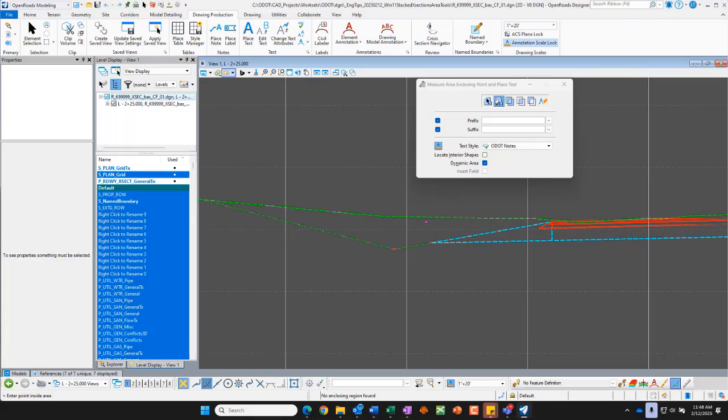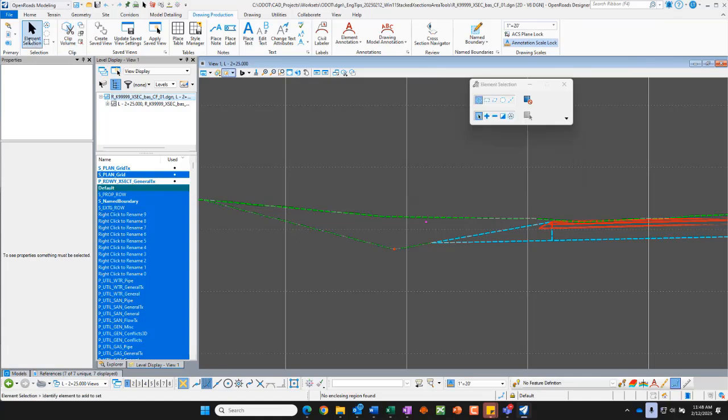It was a great idea, but I think that there is a little bit of a faster way to do this, and I am going to use a MicroStation command, and then I'm going to use a different command, not this one. Let me first use the place shape command, and place shape is on my spacebar pop-up menu. It's in the placement group, so you can choose that, and it's place shape,